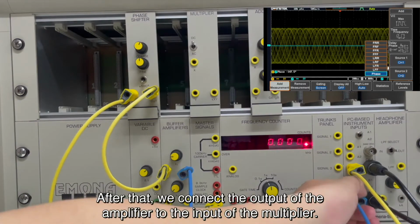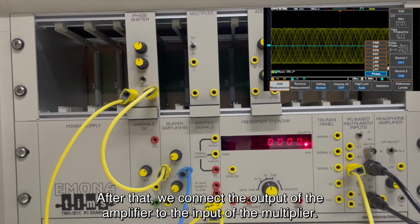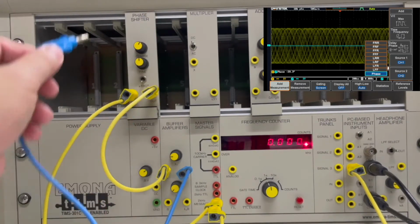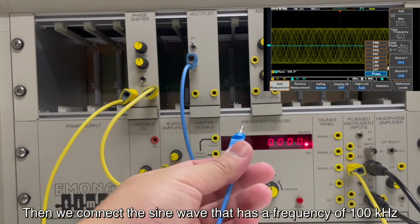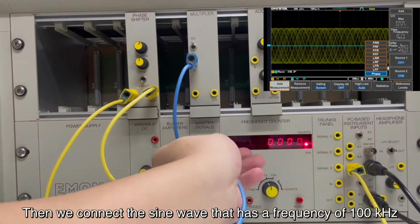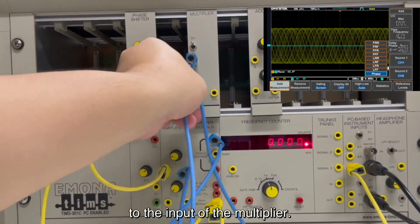After that, we connect the output of the amplifier to the input of the multiplier. Then we connect the sine wave that has a frequency of 100 kHz to the input of the multiplier.